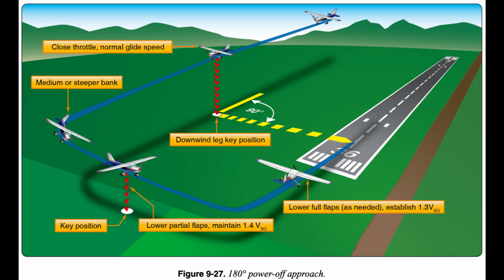5. Failure to lower landing gear in retractable gear airplanes. 6. Attempting to stretch the glide during an undershoot. 7. Premature flap extension/landing gear extension. 8. Use of throttle to increase the glide instead of merely clearing the engine. 9. Forcing the airplane onto the runway in order to avoid overshooting the designated landing spot.